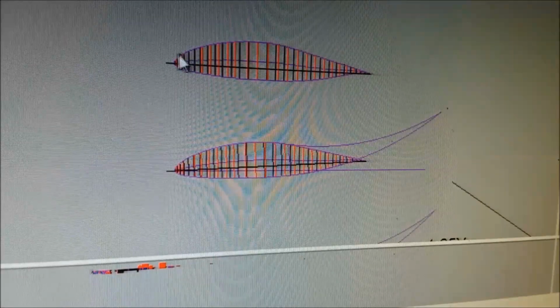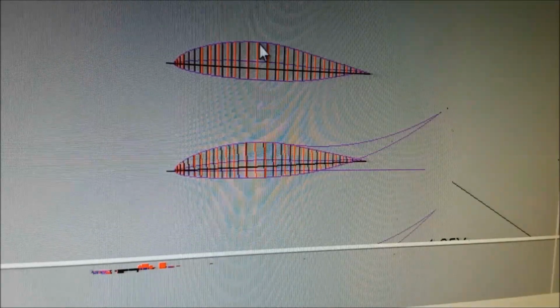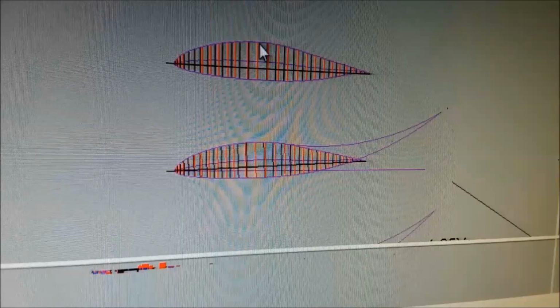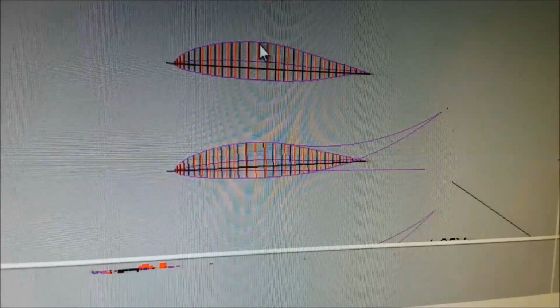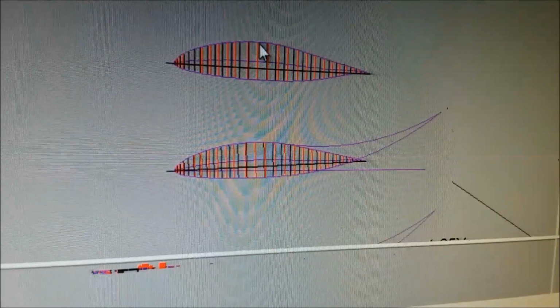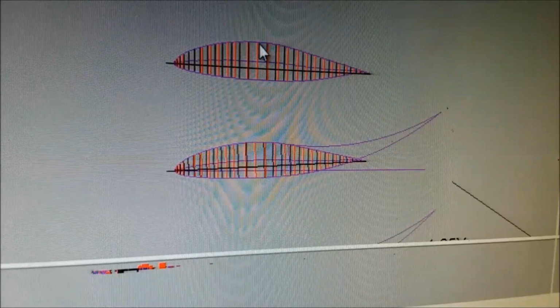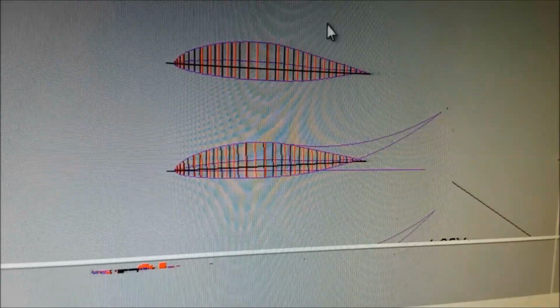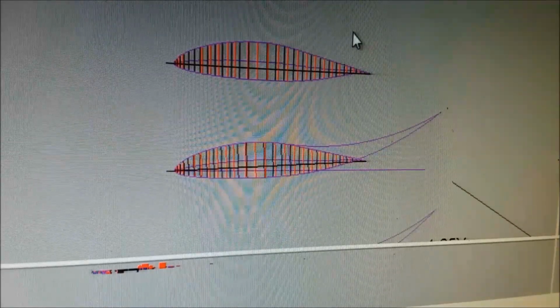You cut it out full scale to what you want for the root, the end at the hub, and the end that you want at the other end of the tip. And you stick them on the ends of styrofoam and look up hot wire cutter. You can buy them, it's easier to make them. You just take this closed cell styrofoam like the Blue Builder's foam. Dow makes it. You can get it at Lowe's and Home Depot, and here we can get it up in Imus. There's 4 or 5 places that make it and sell it.